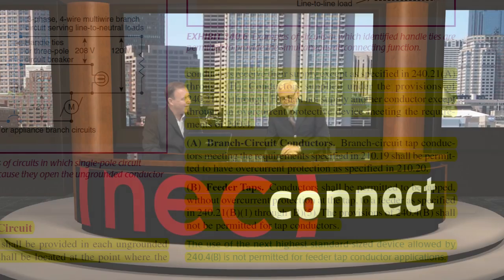Exactly. So when you look at that definition, that has overcurrent protection ahead of the point of supply, that overcurrent protection is protecting the feeder that the tap is coming from. So the ampacity rating of that feeder conductor is consistent with the overcurrent protective device ahead of that. What isn't consistent is the tap from that feeder. Now that conductor is going to be smaller than the feeder conductor itself. Let's move on to branch circuit tap conductors covered at 240.21A.